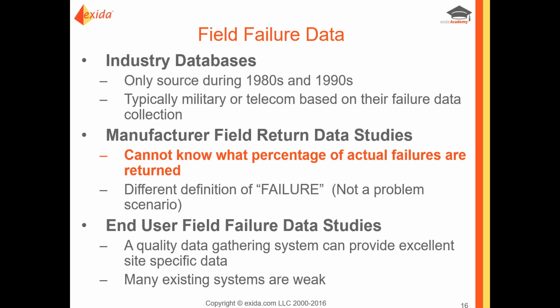Industry databases are one source where many different companies pool together and follow some common data collection procedure. I'll talk about that in a moment. Manufacturers' field return data studies have been done for decades, and manufacturers look for certain things, and that information is also quite valuable. And the primary reason is because manufacturers often will trace a set of failures down to the root cause.